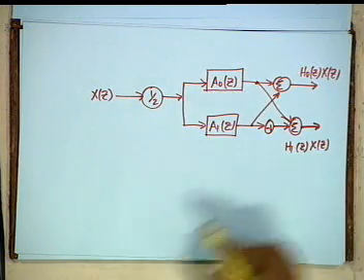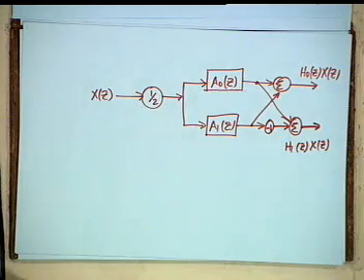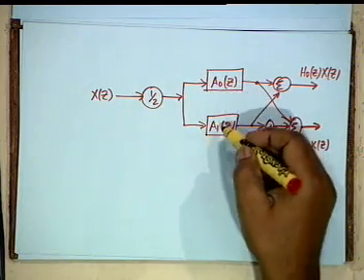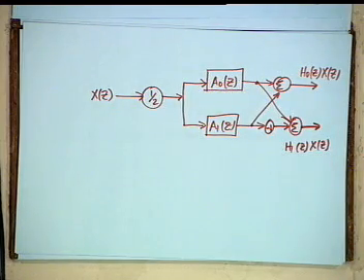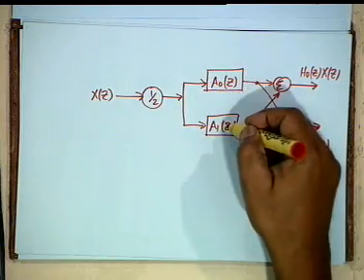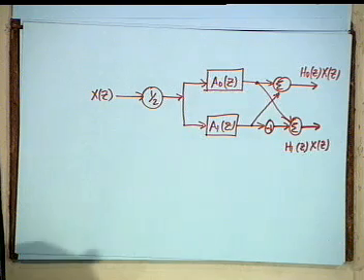all right. Now these h naught and h1 are two complementary transfer functions, doubly complementary transfer functions, and all that you require for their realization are two all pass filters. If you can realize two all pass filters, then you can get doubly complementary transfer functions.